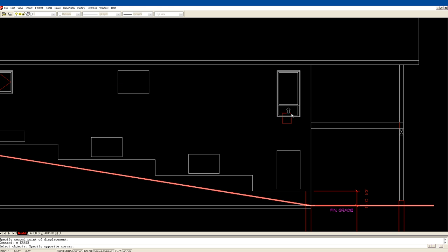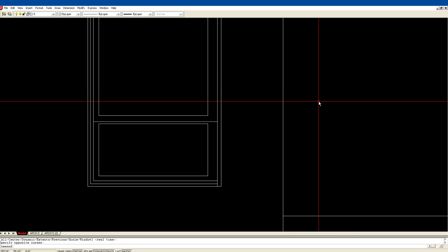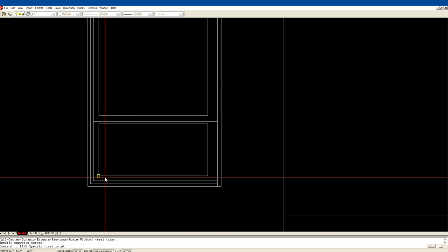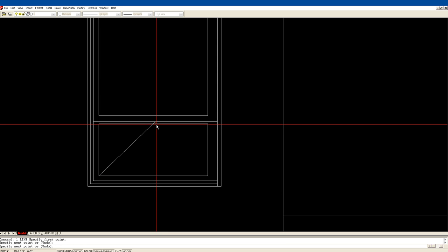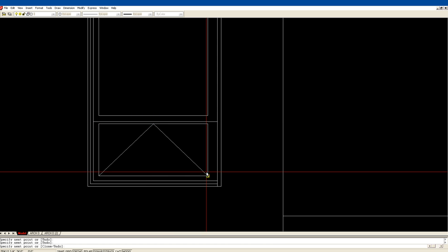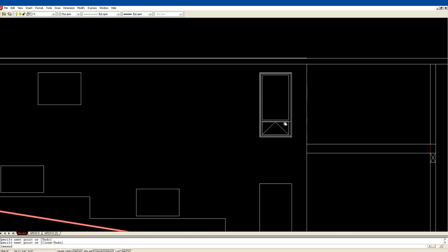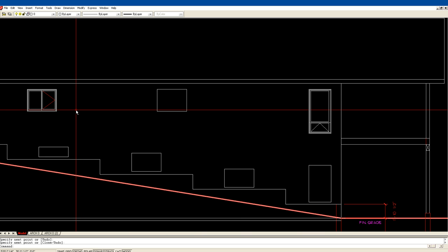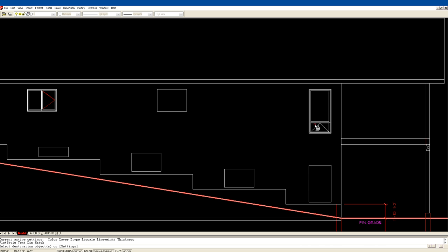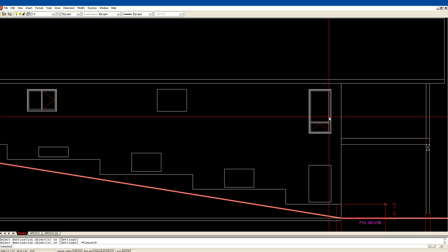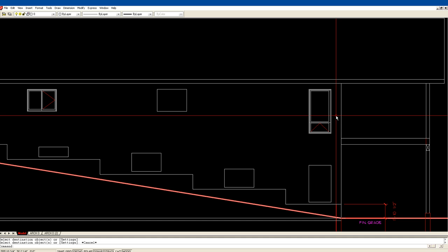And again, if I didn't want it to slide and I wanted to crank, it would become an awning window. So I would draw a line from here, not to there, to there, and to there, and put that on match properties on the hidden layer. Okay, so that designates a window that would crank or lever open, and the hinges would be on the top, and so it would open out.